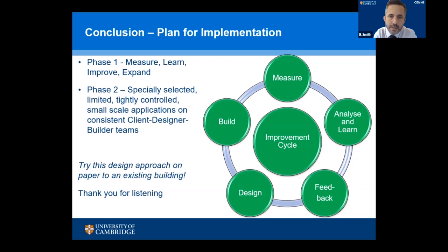Fundamentally, what I'm trying to do here is take the observational method used in geotechnics to improve design efficiency and apply it to the structure. But unlike geotechnics, we can't change the structure as we're building. So initially, I want to calculate the surplus capacity and give it back to the owner so that it can be used for future building expansions. At the same time, that will enable us to improve our understanding of structural modelling so we can apply it to all structures. Does that answer that question?